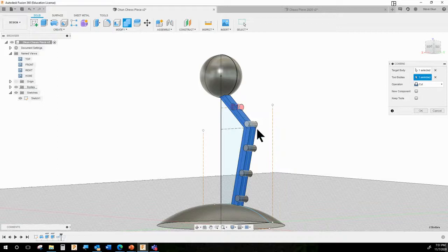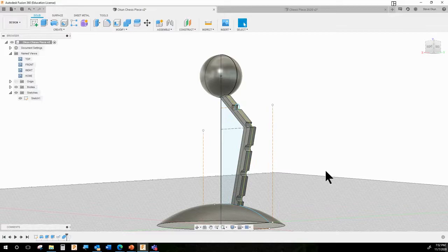And so we are going to choose all the little knobs and it will let us choose as many things as we want to be tools to cut into it, because that's what those little chisels and stuff that a machine shop worker uses are called. They're called tools. A drill is a tool. So we're going to turn these into little drills, basically, by selecting them as our tools. And we could ask them to join, which would just make it one unit. But in this case, it has guessed right. We do want it to cut, and we're going to click OK.